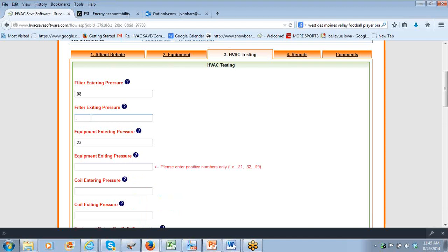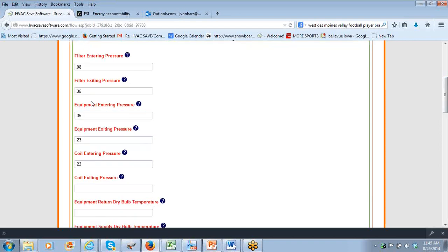I'm sorry, I'm going to actually make these different. I'm following my own startup sheet that you don't see right now. So I corrected a data entry error there. Get these static pressures down to hundredths. Okay, don't take them to tenths. That's not going to be accurate enough.